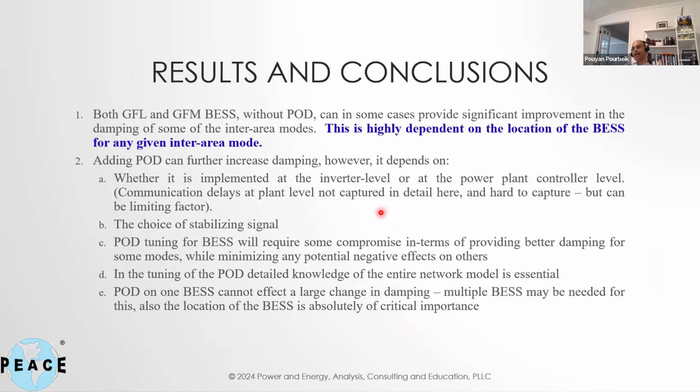Then when you added the POD, you could indeed further increase the damping. However, that depended on a number of things. One of them was where you implemented the POD. At the inverter level, is probably in some cases, if not most cases, more effective than the PPC because of